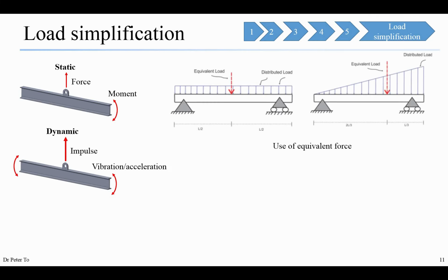Now we move to the second part of this lecture, about the shape functions. For 1D, we know that epsilon equals du/dx, where u is the displacement and ui is a nodal displacement. They are not equal, but we try to calculate the displacement from the nodal displacements, which is done easily by the shape functions. So here is a scheme of how we calculate u and its relationship with x.